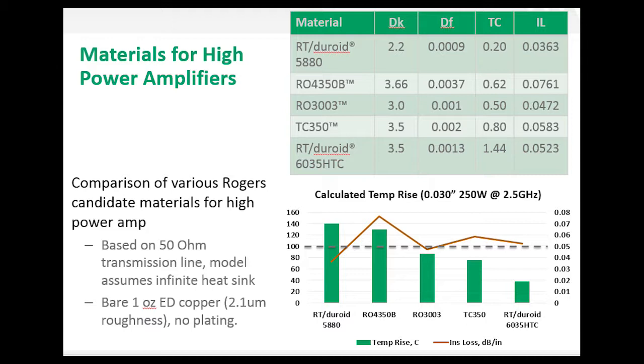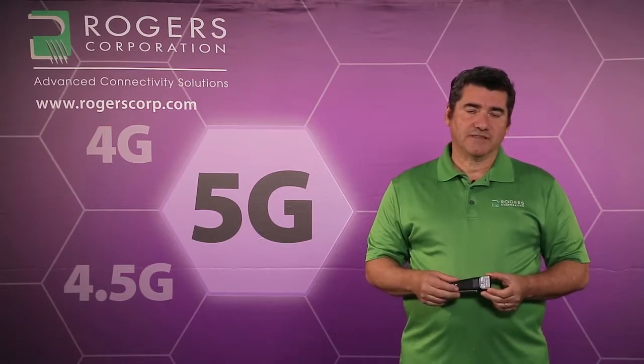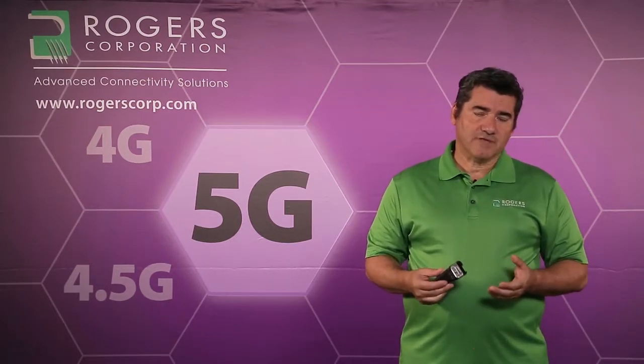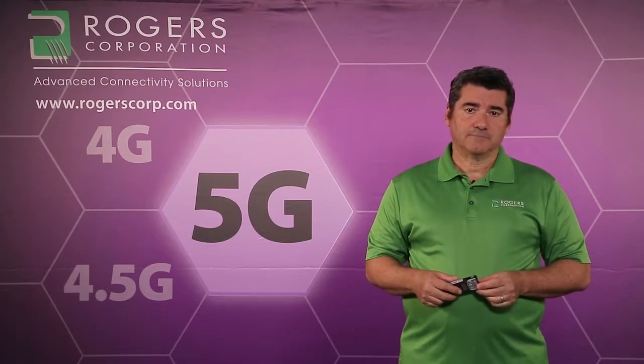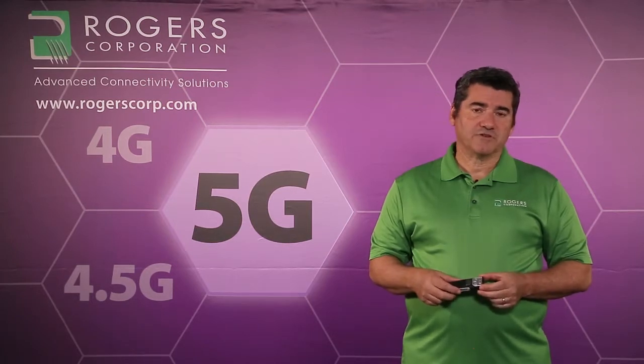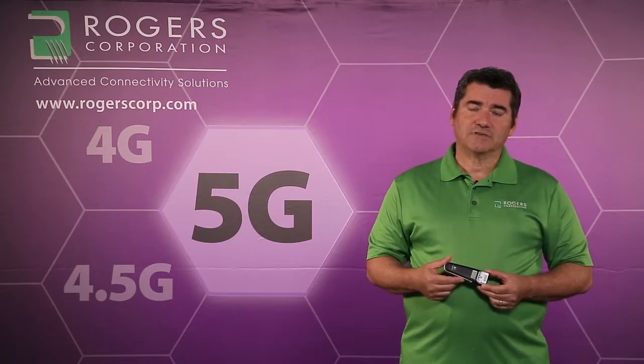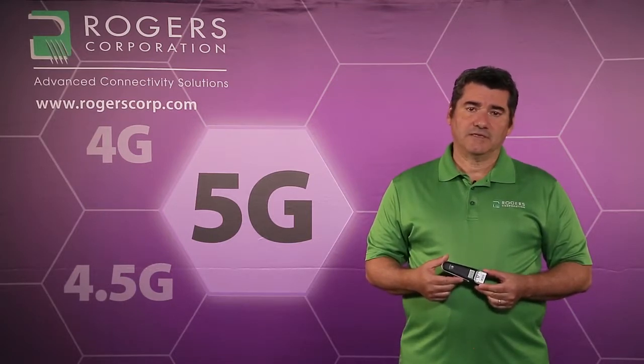So hopefully what we're showing you, the designer, is that as you focus on material need for high frequency, high power application, thermal conductivity is the most important property you should focus on first. Then we can look at loss tangent and dielectric constant. As electrical engineers, we tend to look at every problem and try to solve it electrically. We try to reduce temperature rise by use of low loss tangent. But in reality, loss tangent has minimal impact when you're already working with materials with low loss. Thermal conductivity is really the factor, as we showed in the previous tables, that will affect the generation of heat